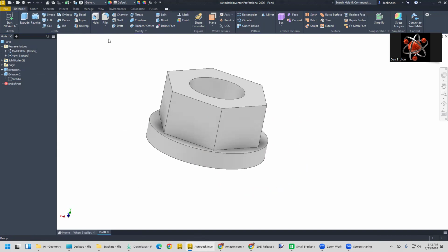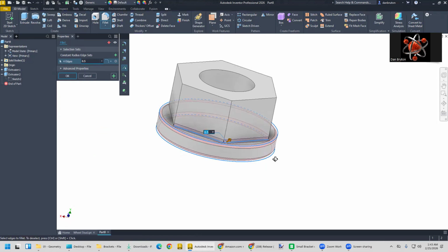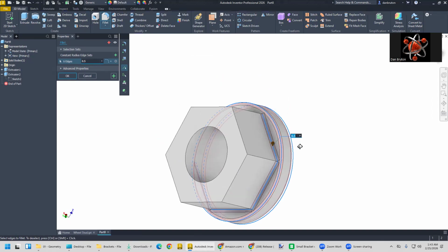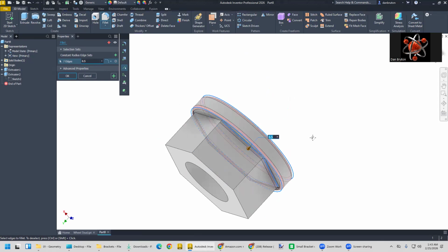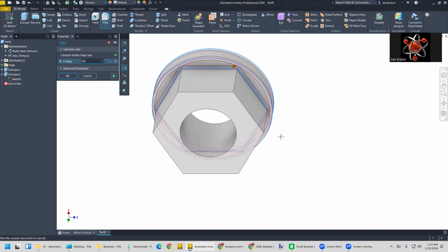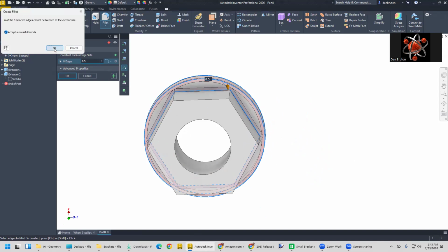Now it seemed like they had some smooth edges to it, so we're going to do a little bit of smoothing. Let's just do a little bit of, let's say, fillets. And I want to say that it's just a really small amount, like 0.5, right there and right there. And that's probably good enough. Yeah, let's just make it smooth and classy here. I don't really know what that green color is. I'm not sure if it's a paint they put on there or a particular kind of metal processing they did. Okay, so we got that. Let's click OK.